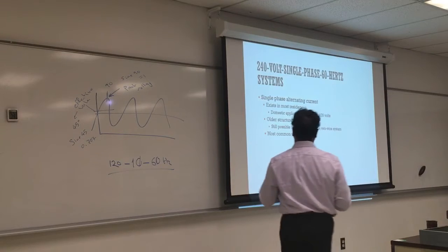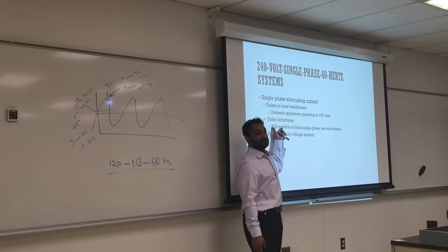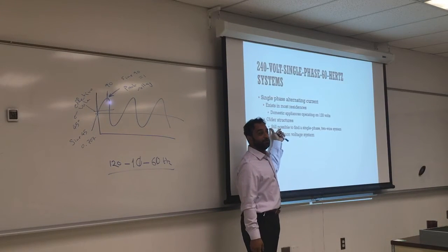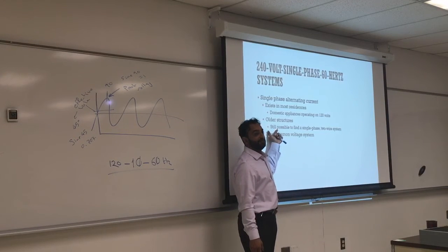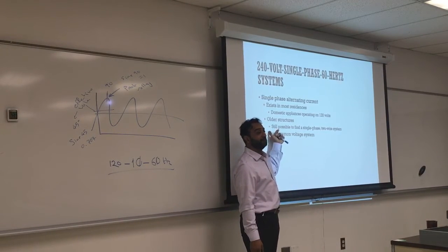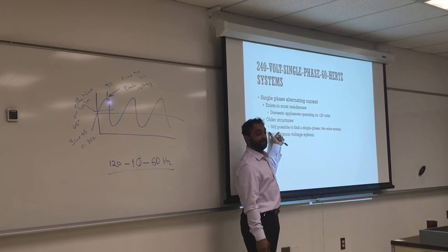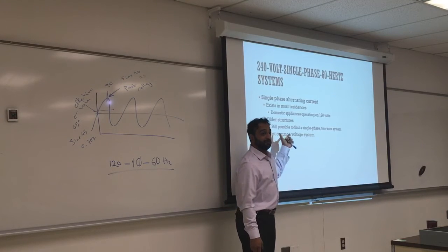All the structures, that's something you're going to face a lot, especially with your mess. You're going to have some old houses. You'll see wires insulated with fabric. That is common. You'll see wires made out of aluminum. And why did they use aluminum? Cheaper. What else? Paper insulation. Tissue paper insulation.